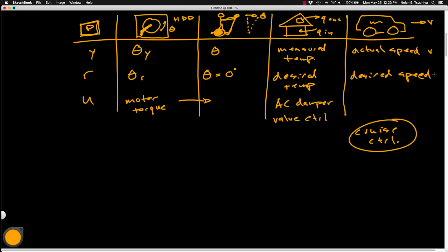And then you can let your foot off the gas, and you notice that the car will, depending on the outside conditions, sometimes go a little bit faster or a little bit slower, but it'll always try to maintain that desired set point speed that you had specified. And the way that it does it is through the control command sent to the actuator, which is in this case the engine. So it basically throttles the engine automatically so that you maintain the desired speed.